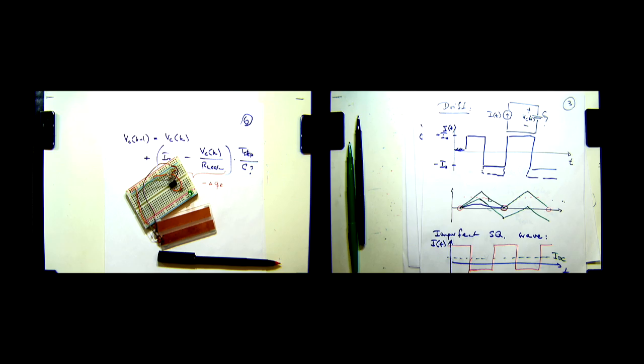Oh, that's a loaded question. But when you need one, just buy the right thing. Just order a comparator, order an op-amp. In the lab, actually, this is something that I distinctly dislike. In the lab, you're actually going to use an op-amp as a comparator. And it sort of works.